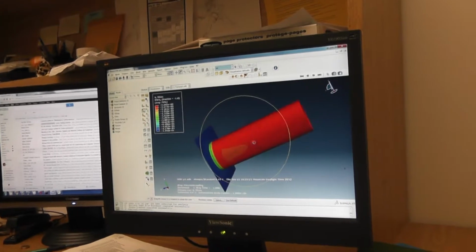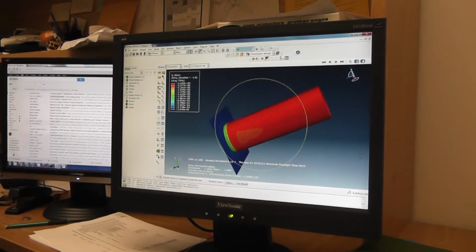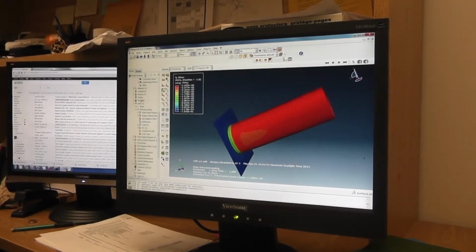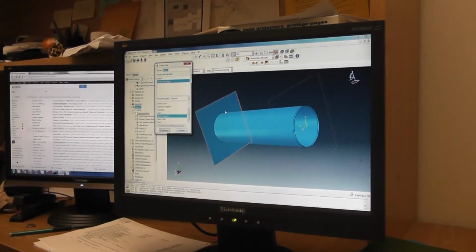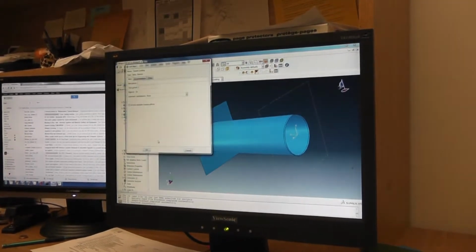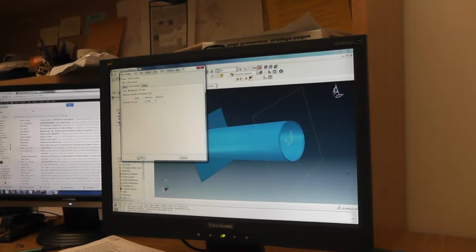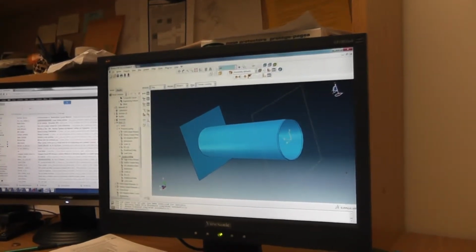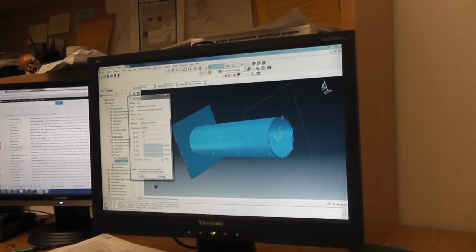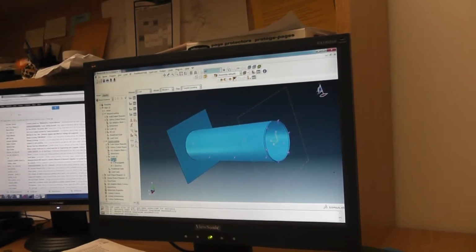Now we want to apply the loading that we want, which is we're going to move that surface upwards, let's say. Alright, I'm going now to go to the model, create another step. I'm going to call it Tensile loading. Now this we want to do in increments, 0.1 let's say. And the second boundary condition, I don't need it. I need another boundary condition.